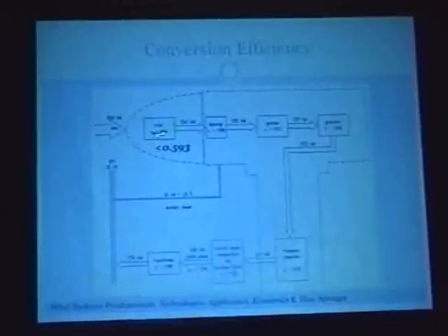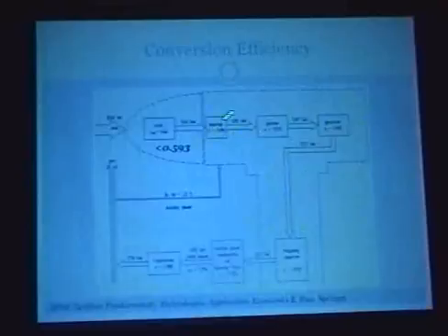So, in going from here to here, you lose very little of the mechanical energy. So this step of the chain is really quite efficient, and it's the step in converting the mechanical power embodied in the wind to mechanical power of rotation that is dominating the losses. And then, of course, you have a transformer that puts it onto the grid.